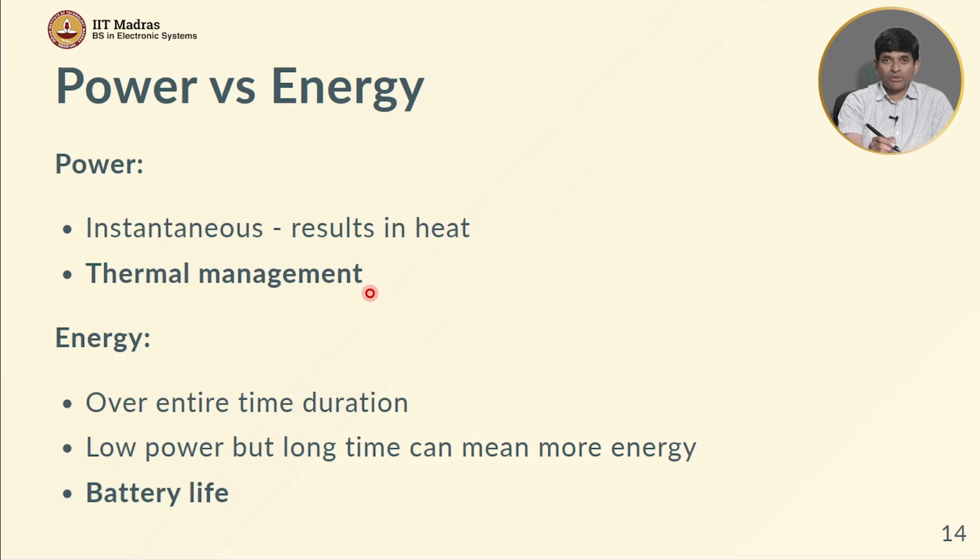Now, let us say that you are building server racks that are going into a data center. You probably can tolerate a fair amount of power consumption, but this is your biggest problem, because thermal management is what you are going to struggle with the most. Because once your systems start heating up, you need good active cooling systems, you need air conditioning, all of that in order to make sure that the system can keep running at high power for a long time without getting too hot. Okay. Now, one of the things, as we saw, is I can do frequency scaling, which means that I can bring down the power.